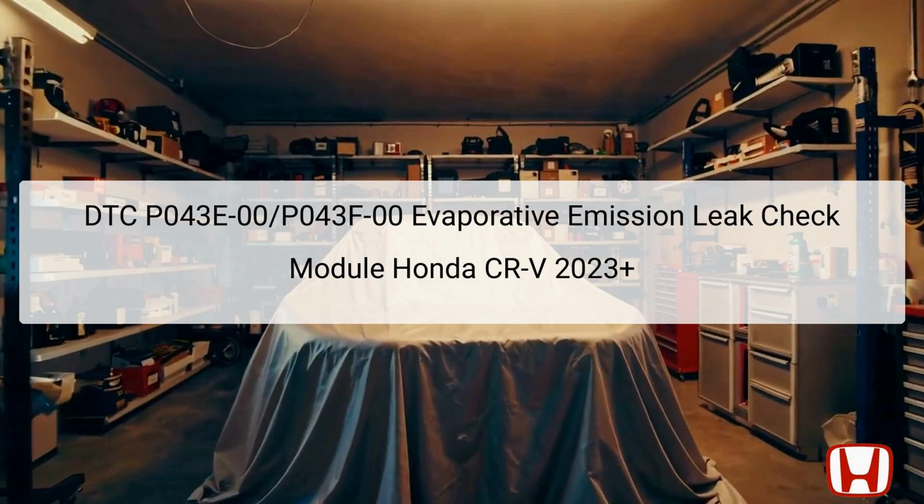P043E-00 suggests that the system is detecting low pressure, meaning the reference pressure of the EVAP leak check module is below normal standards. Conversely, P043F-00 indicates high pressure, signaling an abnormality detected by the Powertrain Control Module, PCM.